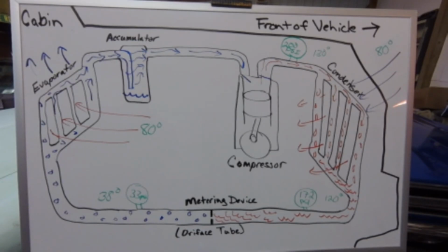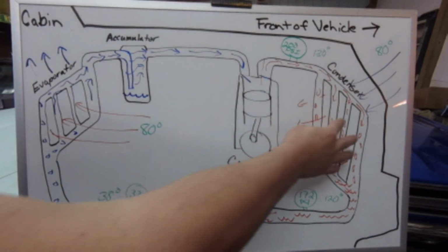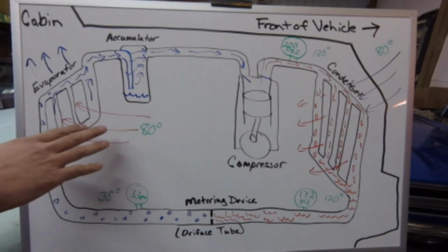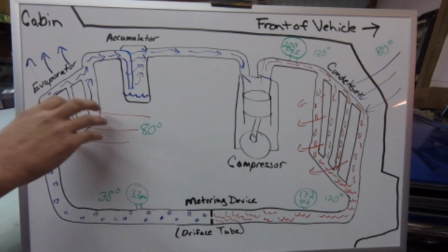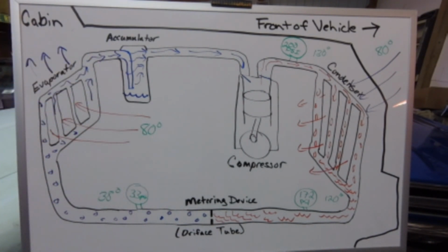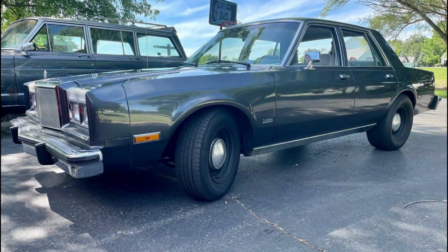So what we are doing here is taking our hot to less hot air and it dumps it outside the car. Same way here. We are taking our hot air and dumping it to our less hot refrigerant. The greater the temperature differential between the mediums, the faster and more efficient the heat transfer is.